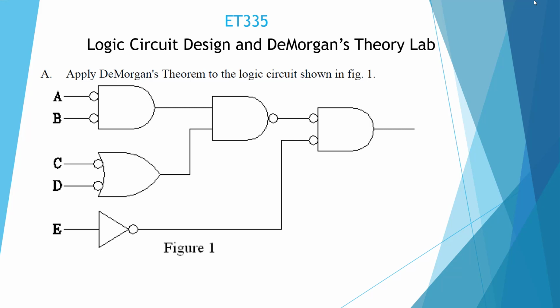The first thing we're going to do is, what is a bubble input NOR, or AND? We're going to change the symbol and push the bubble. So this guy is going to become a NOR. This guy is okay, we have NAND gates in our kit. What about this guy? Well, it's also going to become a NOR.